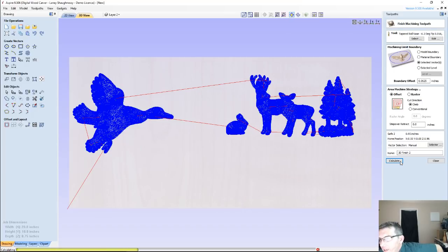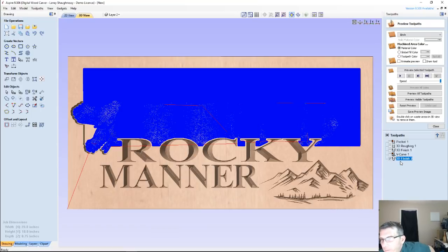Roughing depth. Would it have anything to do with the 0.10 gap above the model? It has something to do with that. You know, that's all added into the Z-plane, which is that 0.4463, but mostly it was because I wasn't doing my subtraction, William. And let's see here. If zeroing from the top, 4463 would be the correct number. You're exactly right, David Garbutt. But with my zero being at the bottom, I had to do the math. I had to do the subtraction to get my cut depth. That's what screwed everything up.